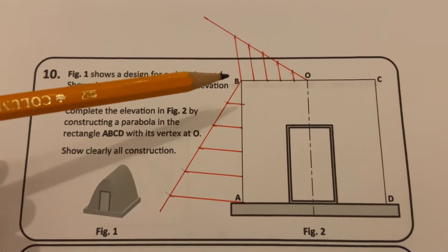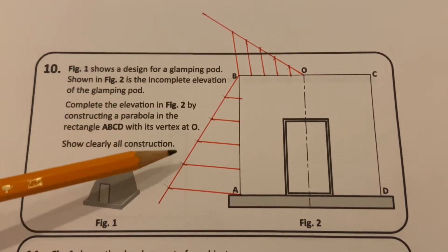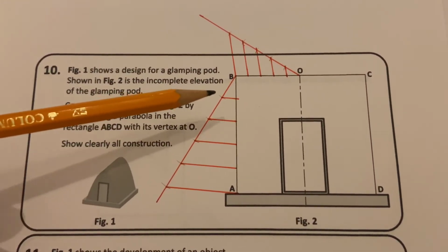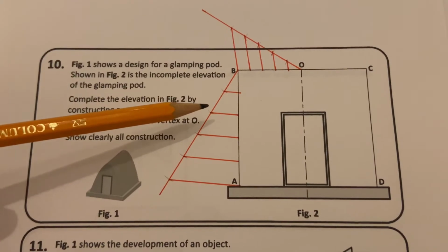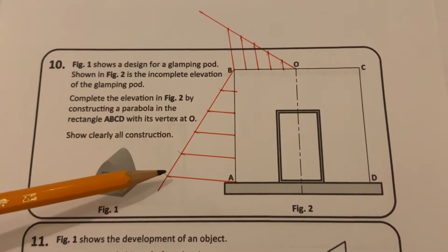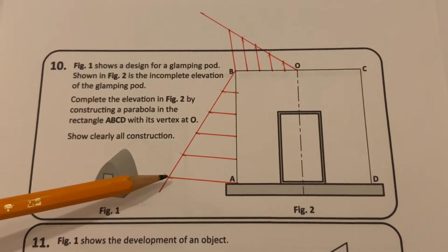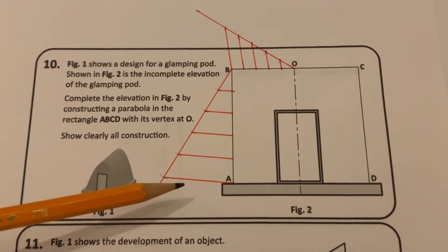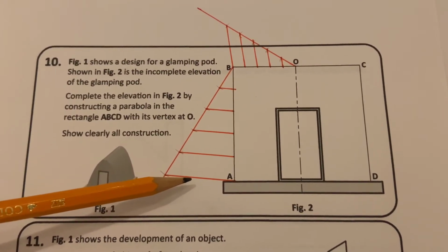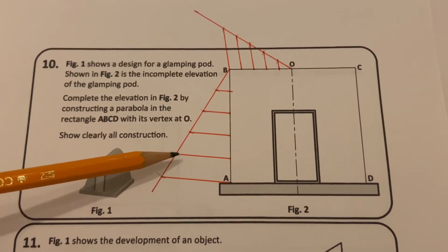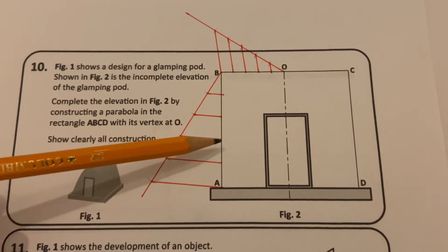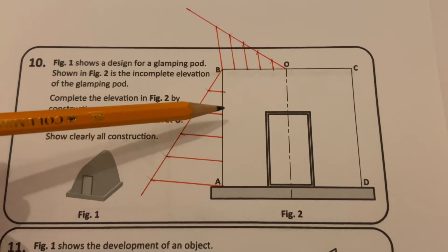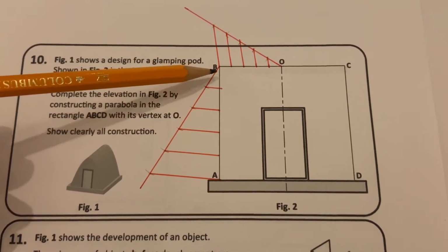So the first thing we do here is we draw a line at any angle from B, and using our compass we step out 5 equal divisions down along that line. The last division we join back to A, and then using our sliding set squares we line up a set square there with this line, and then we go back, bring that point there and that point, and that will divide that line up into 5 equal parts.